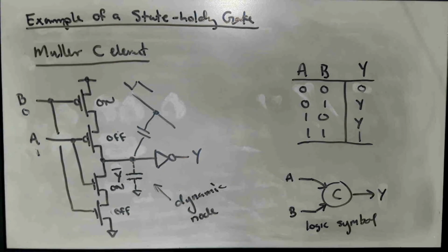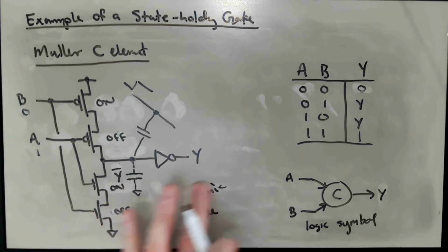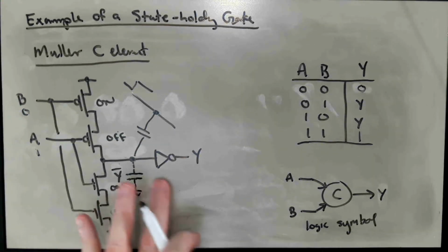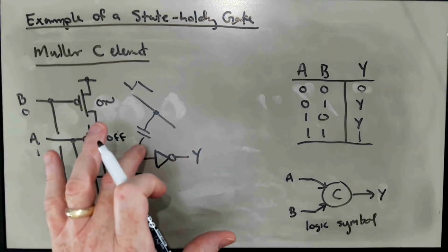Dynamic in this sense is like the dynamic in dynamic RAM. You're basically storing the state, the digital state, as charge on a capacitor somewhere. And with dynamic RAM, you have to actually go back and refresh the charge. You have to read it periodically and rewrite its value before it bleeds away. And so we can fix this and make it static. And we'll talk about that in a minute.